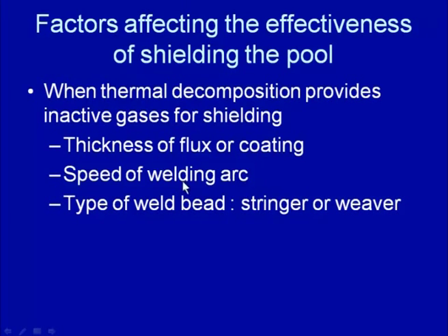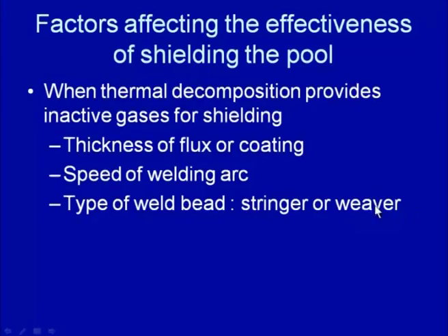The type of weld bead is another factor. In case of a stringer bead, the shielding cover will be disturbed less and will form a continuous cover to protect the weld pool, while in case of a weaver bead, the arc is weaved and moved randomly in different paths, so the protection of the weld pool by this approach is adversely affected. A stringer bead in that way offers better shielding as compared to a weaver bead.